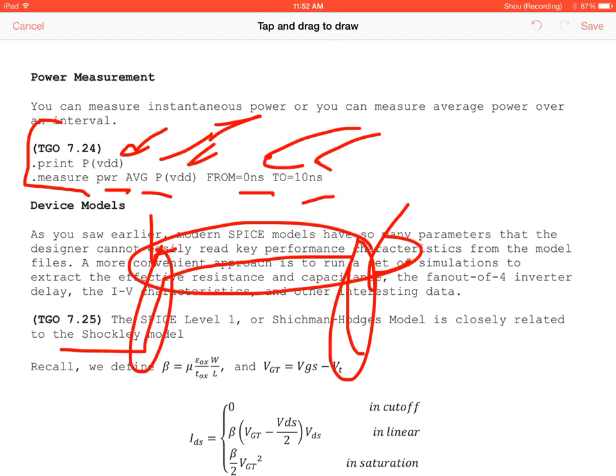So if you're writing some C code or C++ code to generate SPICE, and as part of the process you actually know where your rise is going to be generated, where your fall is going to be generated on every loop, you can use that to then measure the power that's going to happen every time. So that's going back to my dissertation, like I was talking about before, measuring those power spikes. Those power spikes occur during rise and fall. When there's nothing going on, there's no power spike. So if your goal is to do 256 of your S box, and you have 256 different input combinations, and you have to measure the power consumed during every spike for the circuit, that's how you would do this for a specific time.